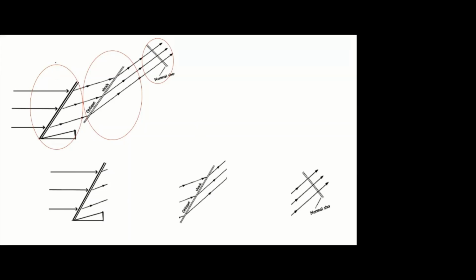so here we have to split this into 3 parts because we have 2 oblique shocks and 1 normal shock. Here they mention the angle is 25.3. Here they mention the angle is 20 degrees. So here the procedure is again. This portion is almost what we found last time itself, in the last case.